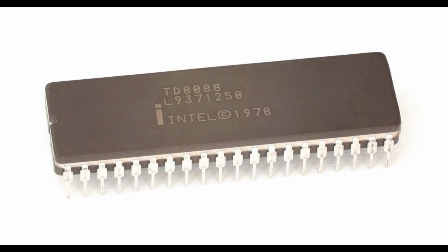So they had the CPU family, but they went after the 8088. The reason behind it was very simple. The 8088 had just an 8-bit bus, and they were able to use well-known circuits. Simply, they had used them in previous projects for Intel 8085 based machines. So this is the reason why I can say that they really used 8-bit machine components in the IBM PC. At the beginning it was not a problem.